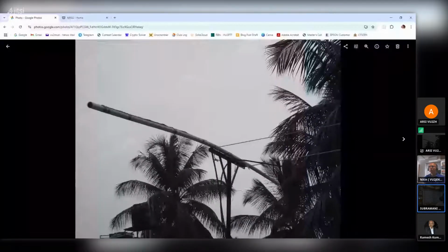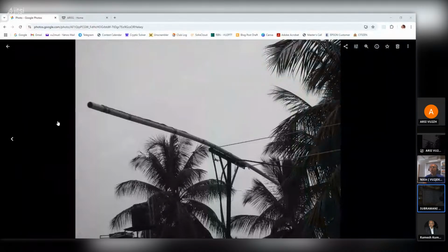In the meanwhile, this is a question from VU2LU: what are the satellites that anybody can work on a simple omnidirectional antenna? Omnidirectional is okay for some low elevation passes, but as I mentioned, it is good to have a simple handheld Yagi. You can use antennas like a J-pole, even a Slim Jim, and any of these can be experimented with, but the preference would be for a directional antenna. As Nitin told, a Slim Jim or a J-pole with about 20-25 watts should be okay. But with a directional high gain Yagi, 5 watts is more than enough, even for low elevation work.